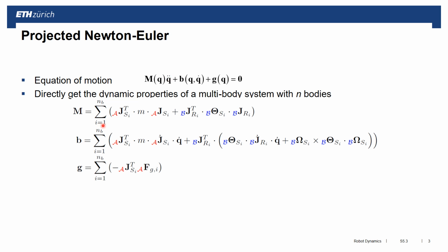That means all we need to ensure is that this mapping that happens here, so the mapping between joint and task space, is such that individual contributions of this mapping have to have the same basis. So I can map the linear part and the rotational part from different base frames, but within individual contributions, they must be the same basis frame.